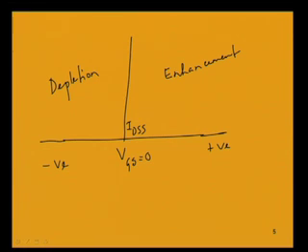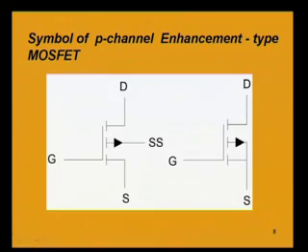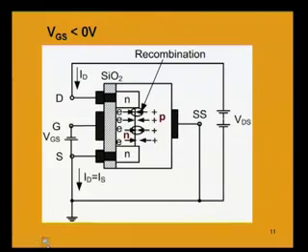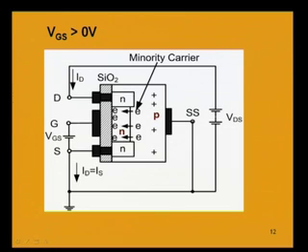So, although the name of the MOSFET is depletion type, actually both the depletion and enhancement phenomena are occurring depending upon the gate to source voltage, whether it is negative or positive. Now, after knowing all this about the different regions of operation, knowing about depletion and enhancement, that is whether VGS is 0 or negative or positive, we can now plot very easily the VI characteristic.